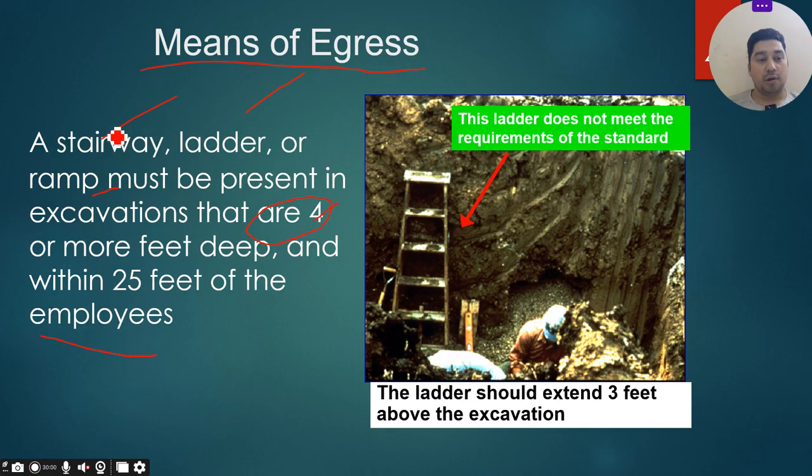And when you are providing any one of these, it should be within 25 feet of the worker. If the worker is working here, then the ladder distance should not be more than 25 feet. This is the requirement by OSHA.